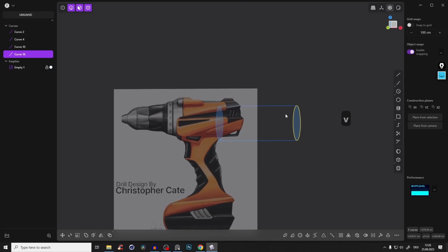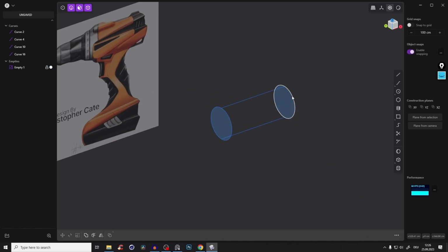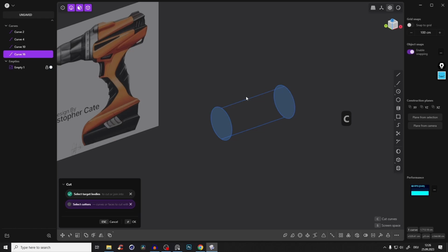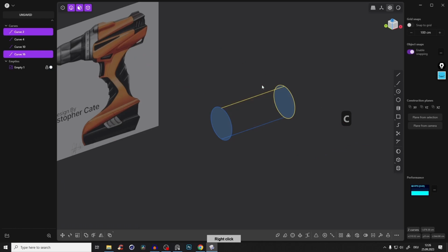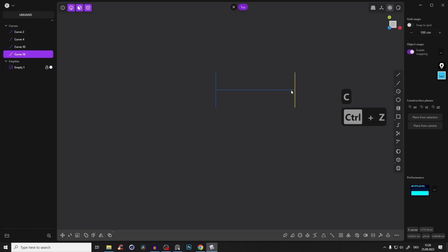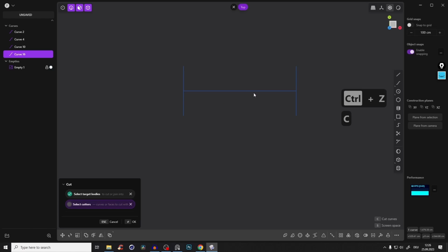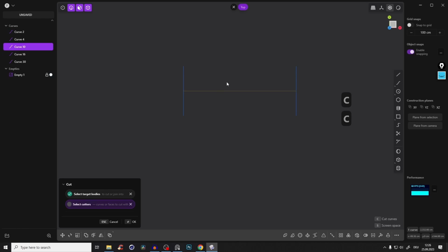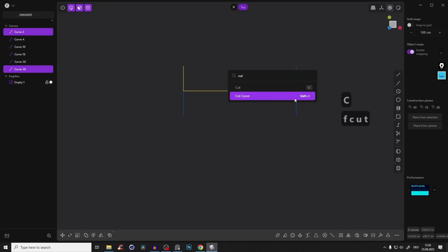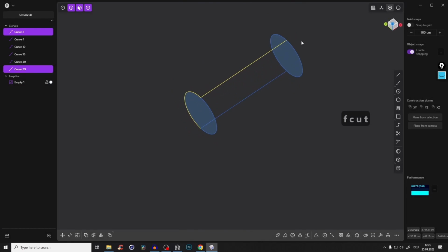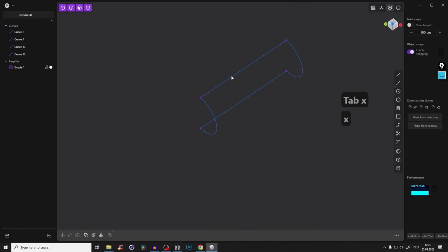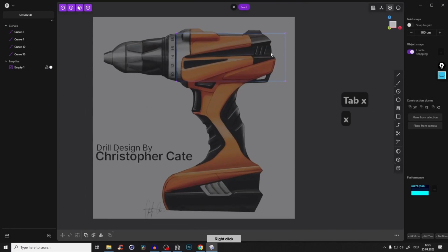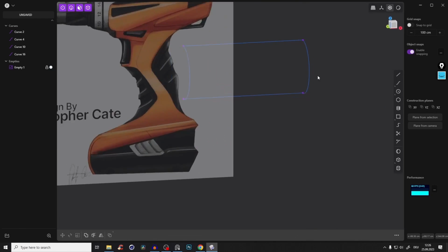And now let's cut those circles in half. Very simple. Select that curve, press Shift C or cut curve and cut it with this one. And so we have to go to the top. So select this, Shift C or search for cut curve and cut it. And let's do the same here, Shift C. So here, cut curve, Shift C, but as always, everything is in the PDF. So let's delete those pieces here and we have basically our shape.